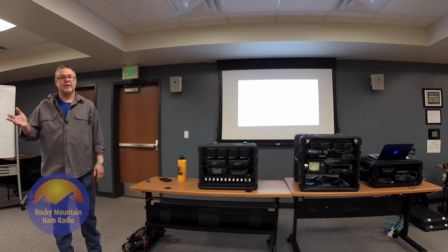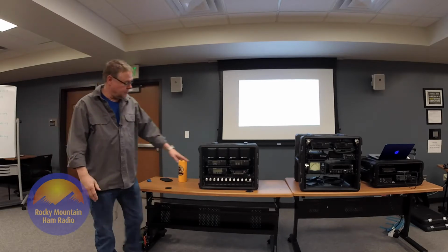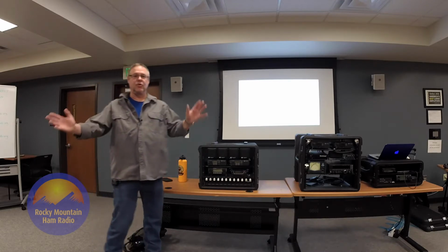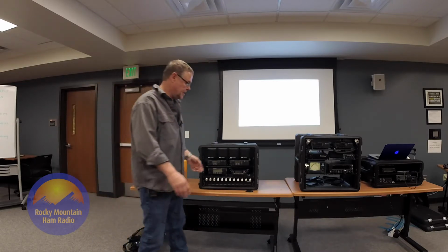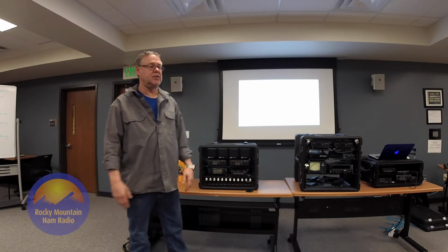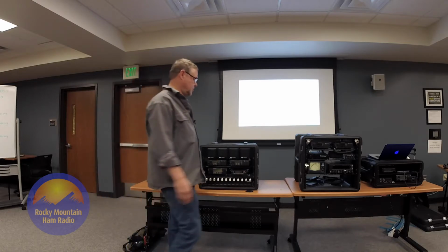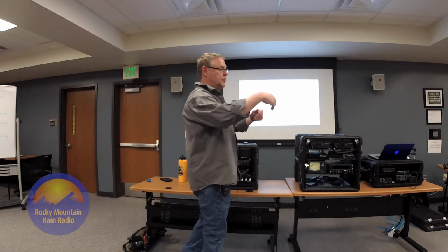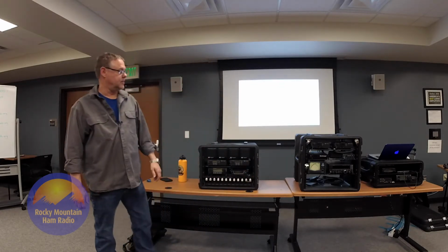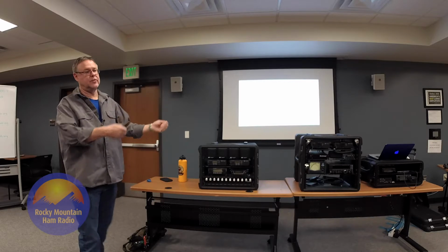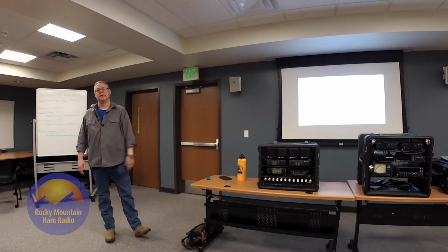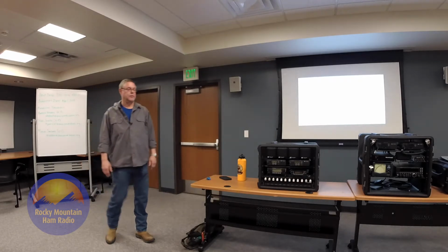Another thing is versatility. If you have several of these shelves pre-built with different configurations, and something's coming up where you don't need the DMR, you need 2 sets of VHF, UHF, ham grade transceivers, you have that shelf already built up with its couple of pigtails sticking out. Pull this one out, unplug, unplug, unscrew. Slide the new shelf in real quick, plug, plug, screw. Boom, you're reconfigured, you're out the door. And it's ready to go.